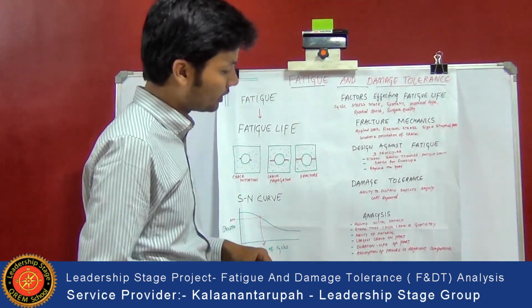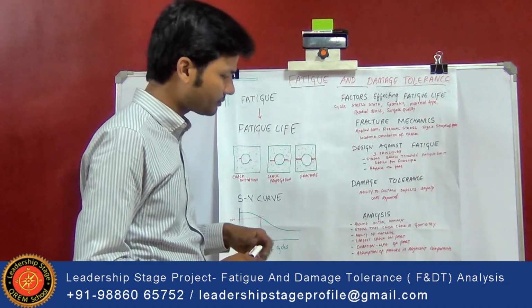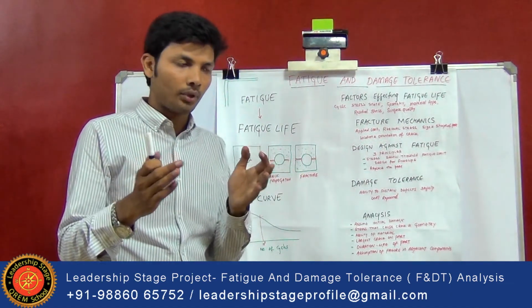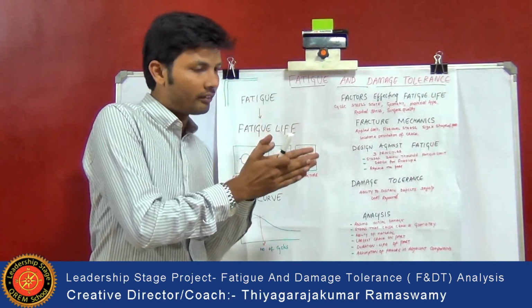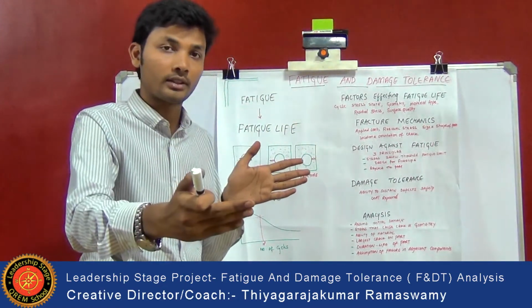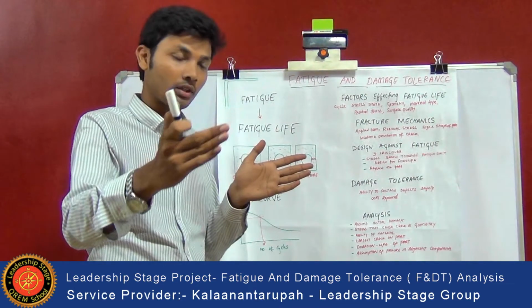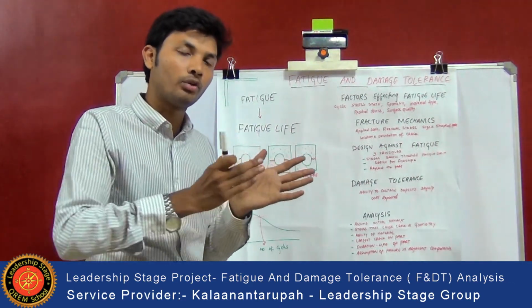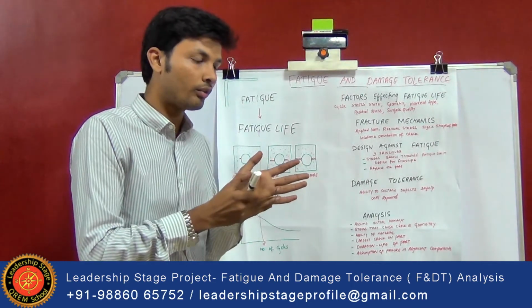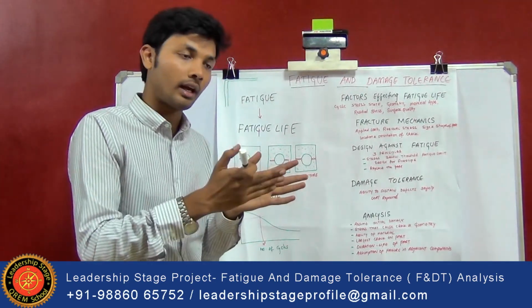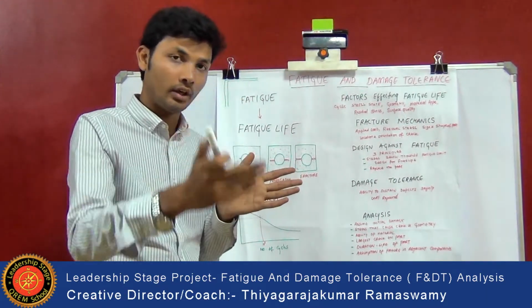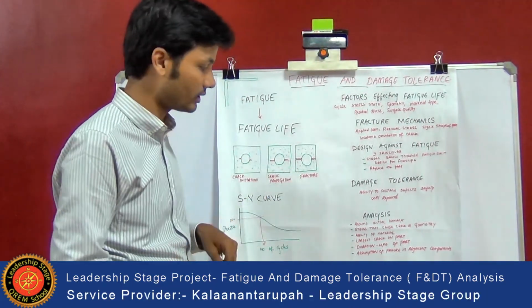And the second is the duration, the life of a part. Here you need to see, from when the manufacturer releases a component to the fracture, what the duration is. We need to see how long it took for the component to get the crack and then to fail after leaving the manufacturer. This will help in studying the component for the damage tolerance analysis as well.